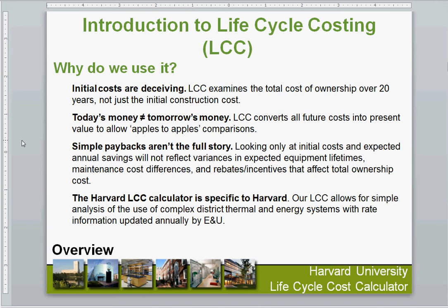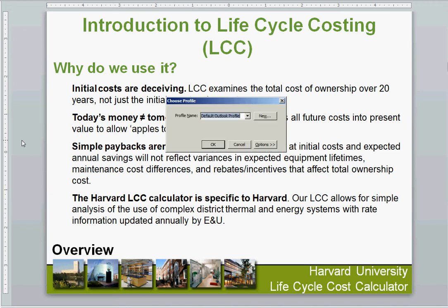And it's going to be a very large number in most projects. So the notion of, well, I could cut out $700,000 from my lighting budget if I switched from LEDs to fluorescents, for instance. Or, we could go with a non-condensing boiler and save 15% on our HVAC costs. Well, those initial costs, while they represent big savings, have big operating cost impacts. So we really want to look at the full cost of what's going on and what those decisions are doing to our long-term cost frame.